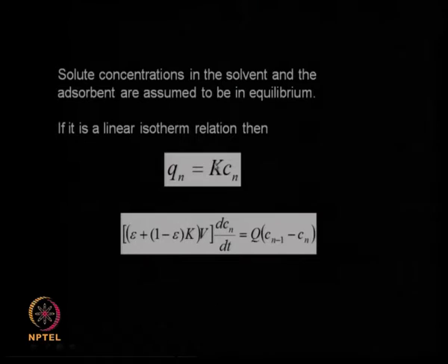So, by putting in the value for Qn like this, we can rearrange the equation to get a differential equation like this. So, K into Cn minus 1 is the amount of solute entering stage n, K into Cn is the amount of solute leaving stage n. This is equal to a big number here times dCn by dt. Now, this is called a differential difference equation, because I can have many equations like this, one for each stage: stage 1, stage 2, stage 3, stage 4.